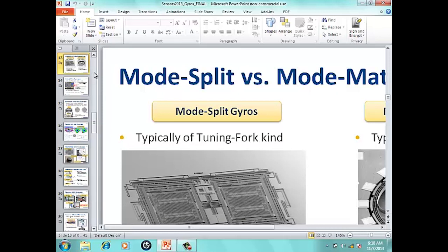Yeah. So it means the scale factor defines the conductivity. Or we can say it's the resolution. Resolution is defined by the noise. Right? Yes, that's the noise. Yeah, and then there's another term called dynamic range, which is basically the ratio of your maximum detectable signal over your minimum detectable signal. Well, yeah, it's a function of the resolution as well.